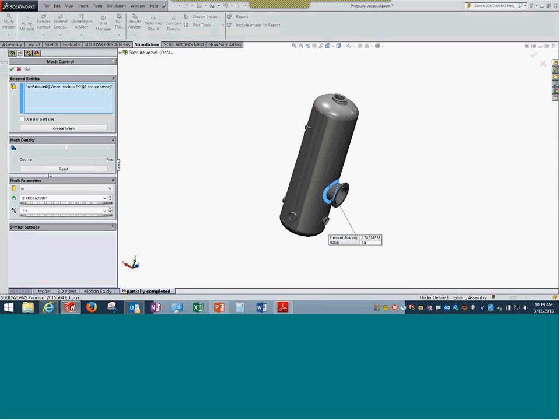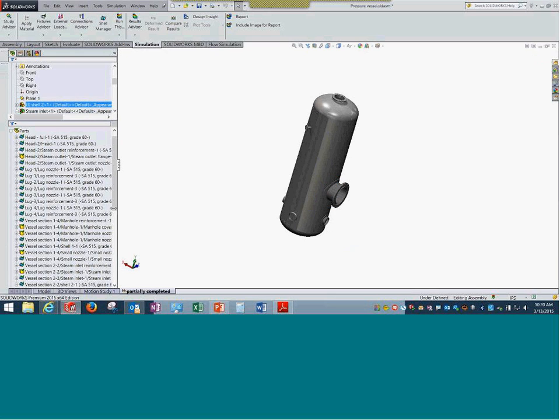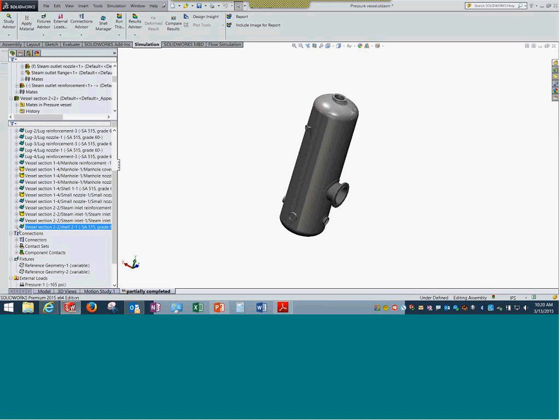So first of all, to get this part meshing, you can right mouse button click on that part and start meshing it. Second, play with the size of the mesh, etc., and you can manipulate all the finer details. On doing that, it will try to remesh only that part with the dimensions or features that you have given.